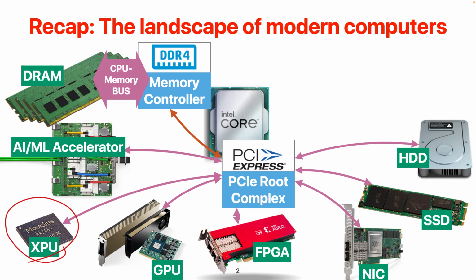But no matter what kind of PU it is, whether it's TPU, XPU, or whatever, it's some kind of hardware accelerator that is domain specific. And last week, we also talked a little bit about FPGA. A lot of people are fascinated by the idea of FPGA in that you can implement application-specific hardware but still make it reconfigurable. FPGA is good for its flexibility. And another reason Microsoft claims they like the idea of FPGA is because you can basically reuse the same FPGA for years.